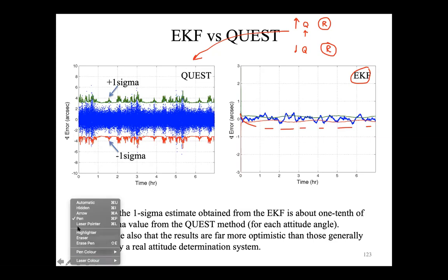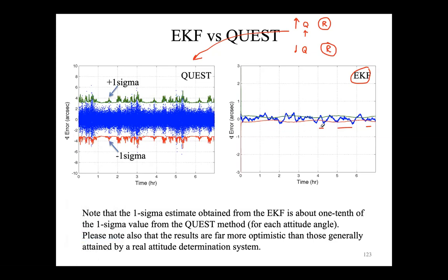And as I said, if you want to face the problem correctly, you should propagate it by integrating the transition matrix times the matrix G. But if you want to do a rule of thumb estimation, you can, for example, try to scale Q in a certain way with respect to R to have the best response of your system. So with that, I would leave the floor to Paolo Cappuccio so he can share his screen and show you some examples. And we can use the break for questions.